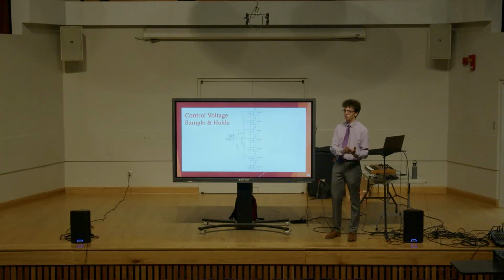If you switch control voltage 1 through channel 1 from the multiplexer, and then turn the multiplexer off and switch to channel 2, that channel 1 voltage is held by the sample and hold and is output at that voltage for probably 6 milliseconds before it starts leaking. So you have to be running this very, very quickly to keep refreshing these sample and holds. But you have sample and holds implemented for every single control voltage that you have to implement for your circuits to work.